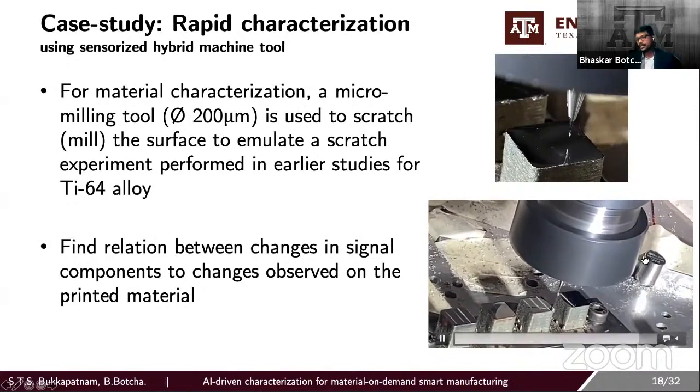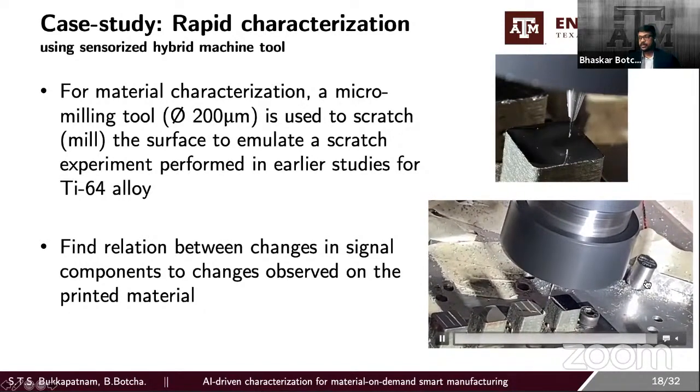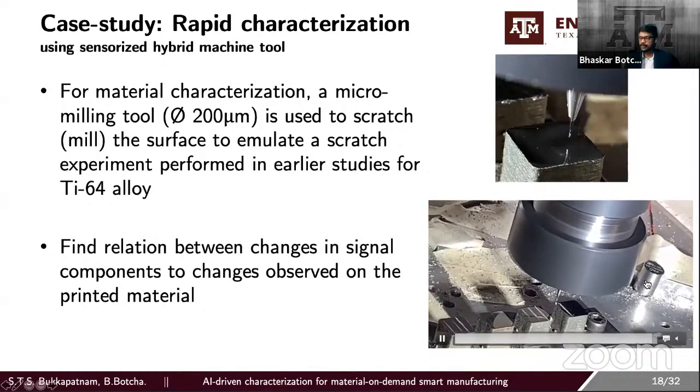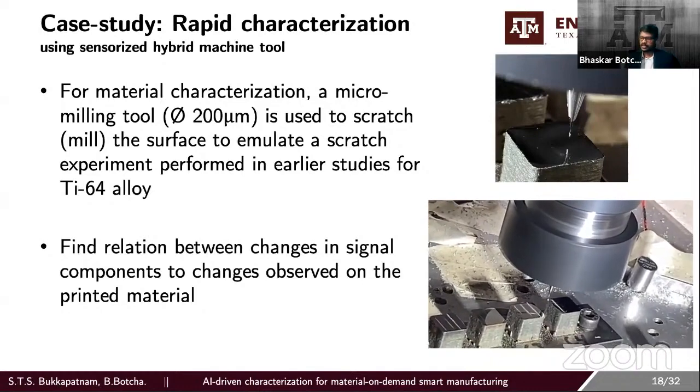So whenever we are capturing these particular signals, when this cutting operation is happening, what we want to see is, can we do a very similar analysis, get the frequency components out of the signals which we collected, extract features, and use the features to predict my hardness, and see if that makes sense. See if we can actually predict hardness from these signals. So that's the basic idea.